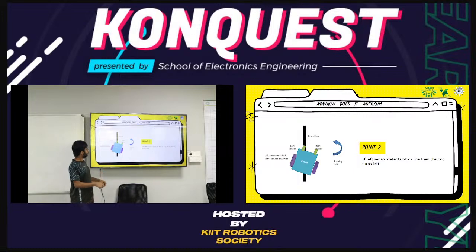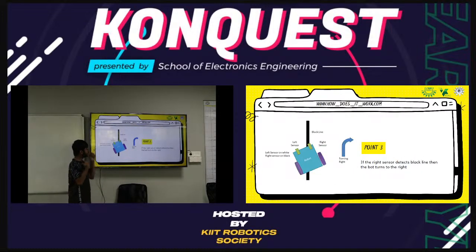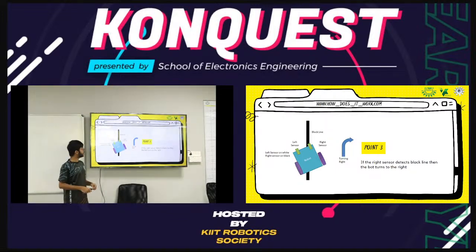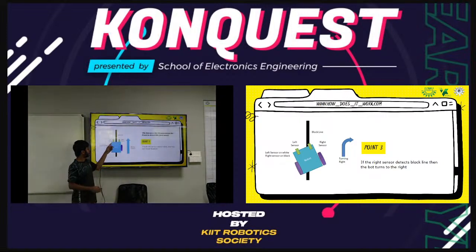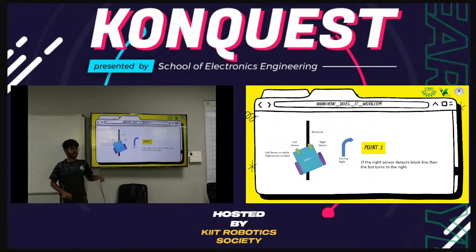All right. So what if the reverse thing happens? If the right sensor is touching the line, that means the line must have turned right. So what we'll do is turn the bot to the right, so that the previous condition comes back, and this will be everything you need to design about the algorithm. So these are done with the two IR sensors.